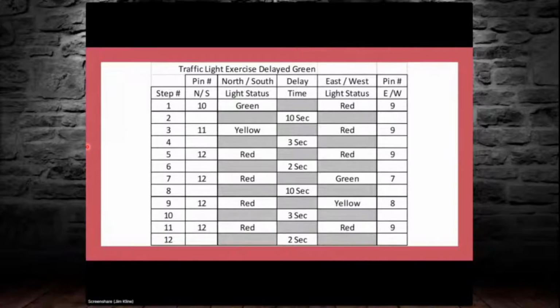Note, the Arduino can only power a limited amount of devices. For this project, there were only 2 sets of LEDs on at any one time, and that will not tax the Arduino's ability to power them. If, however, we were planning on activating a high power device, for example, a 12-volt automotive bulb that draws several amps, the Arduino wouldn't be able to handle that amount of power directly.